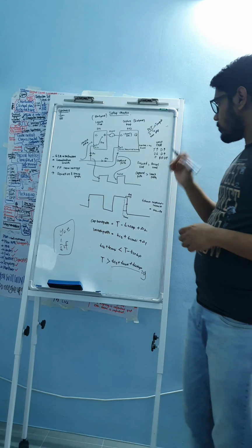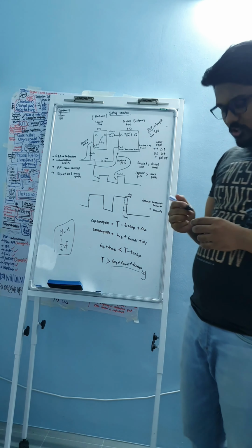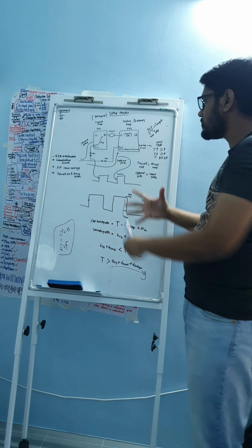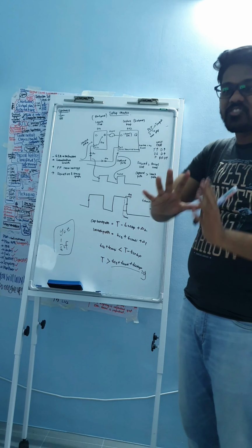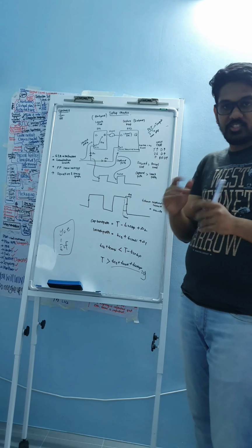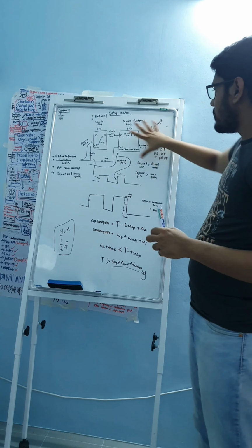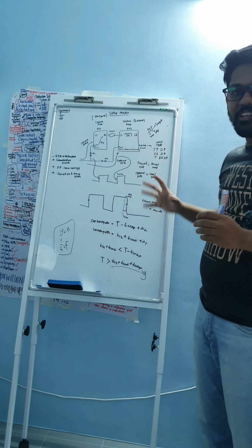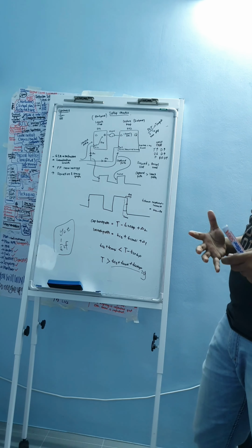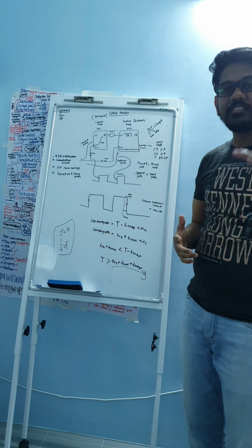So you need to understand why we have this as a worst case, because we are giving the worst performance to the maximum check. For the hold, we are giving the best performance for the data path check. So that's the reason all this will be seen as data path. You make it a worst case so that you are able to converge it at the most pessimism level.